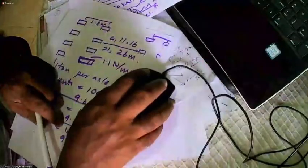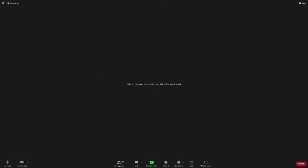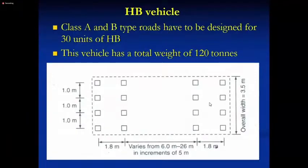So if I stop this and start here, can you see the size is square, and based on the weight, you have to find the size of the wheel, size of the contact surface. Contact pressure is limited to 1.1 newtons per millimeter square or 1,100 kilonewtons per meter square.